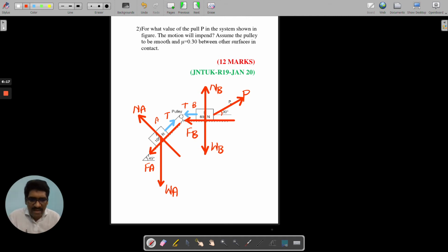Okay, now I am resolving into two components, all of you, like this. Resolving the weight into two components. One is this one and one is this one. About resolution I told everything clearly, all of you. So this has to become definitely how much? So W multiplied by sine 45. You can check my previous classes. There I told resolution perfectly. Now this is the complete free body diagram for the entire system, we can say.